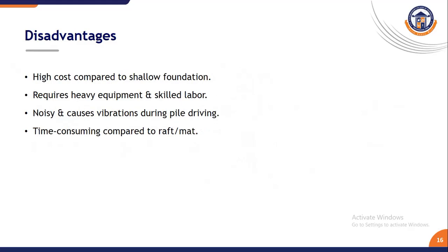Right? And finally, the demerits while using the pile foundation: it is more expensive than shallow foundation due to the heavy equipment and specialized labor required. The installation process is noisy and causes vibration, which can disturb nearby residents or damage nearby weak structures.